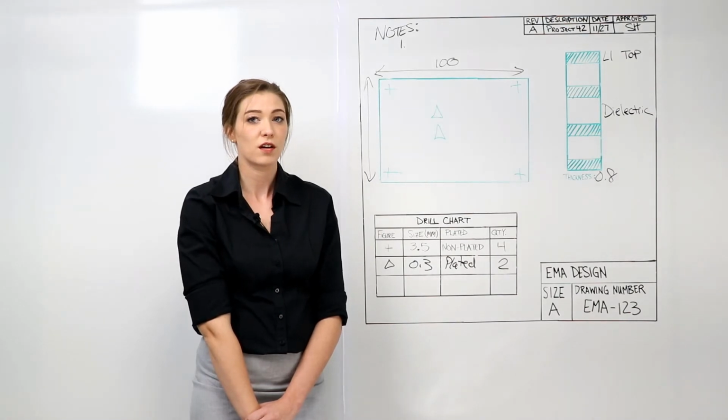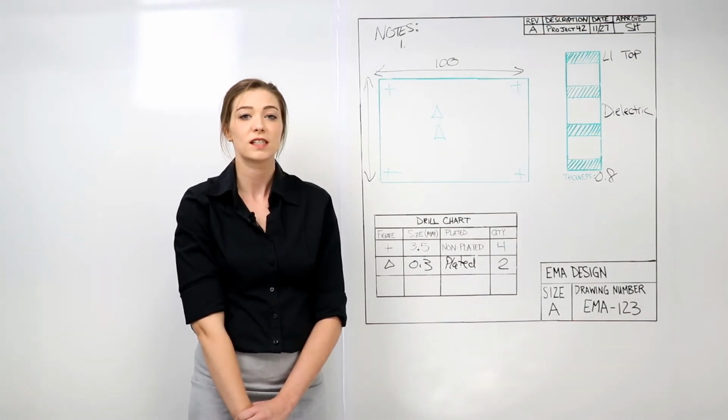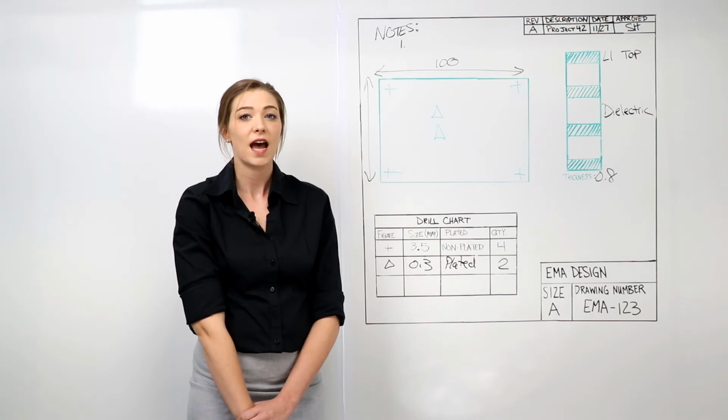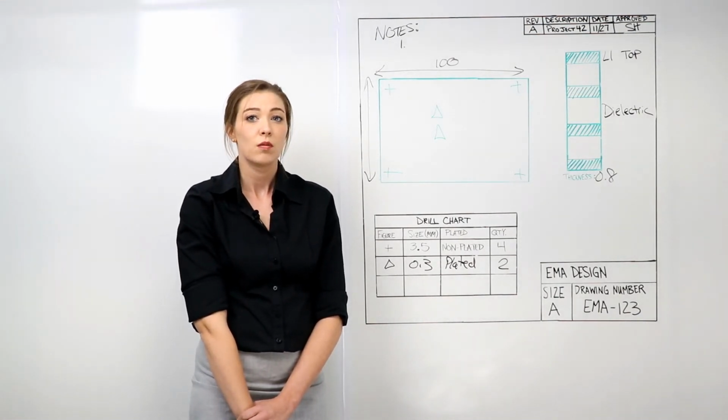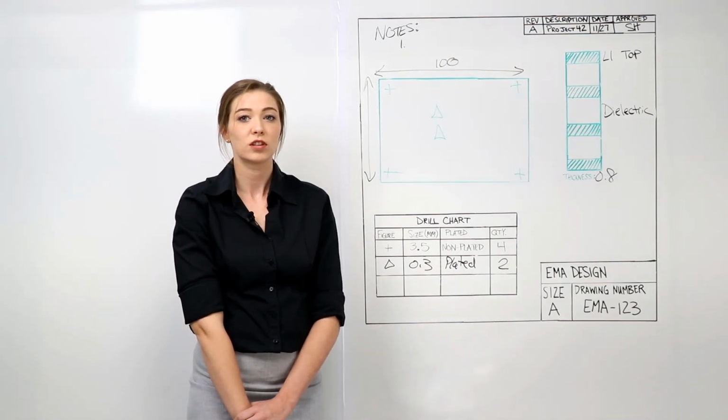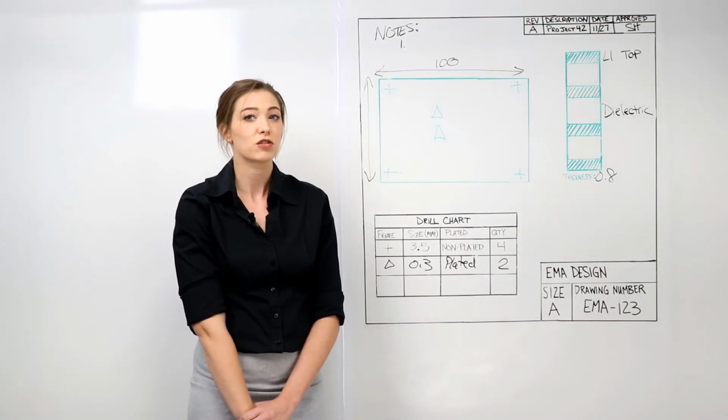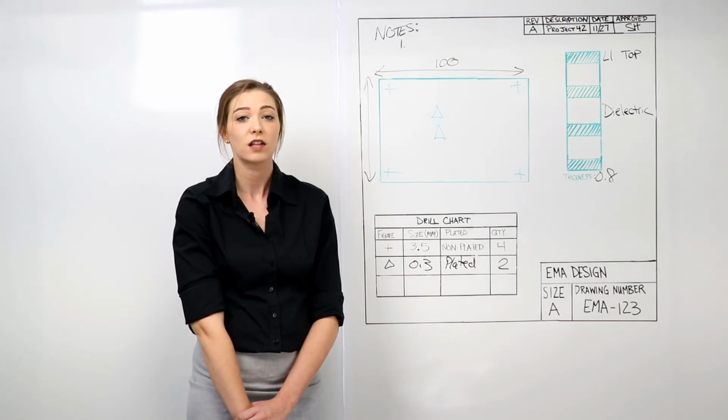Also include fabricator information, which is typically placed on the secondary side of the board, and add any other notes that may be needed for the manufacturing process. Providing a detailed fabrication drawing will reduce questions and errors during the manufacturing process, keeping your design on time.